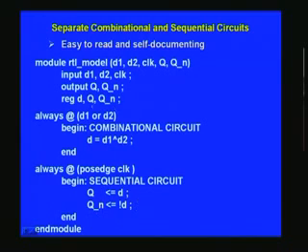And another thing is, if you code it like this, segregating the combinational circuit and making it different from the sequential circuit, it will be very easy to read your code, and you can minimize your comment writing also. That is itself a self-documenting feature, and that is the advantage in following this RTL coding style. This is a typical model of RTL coding.